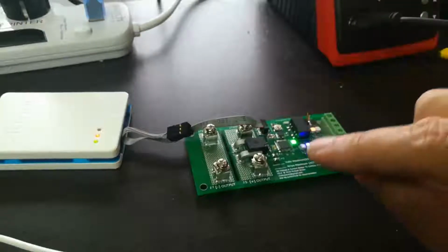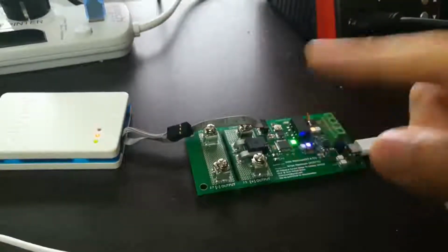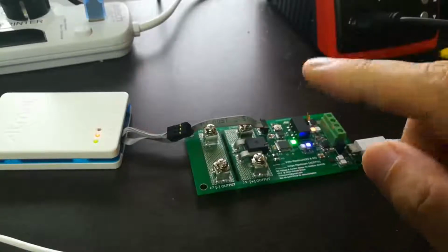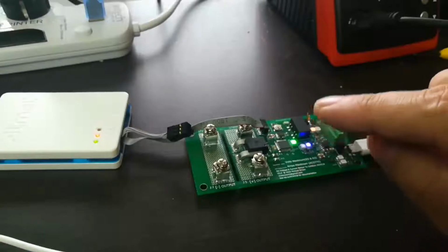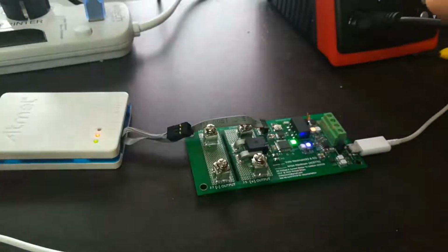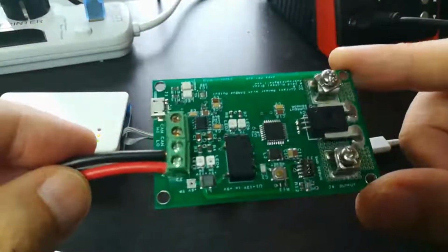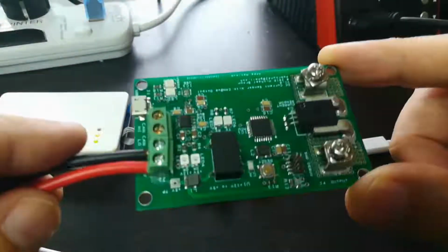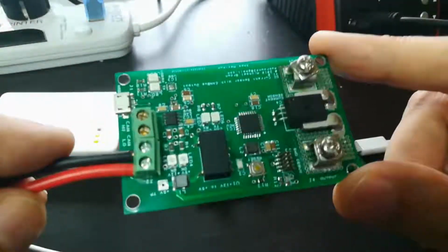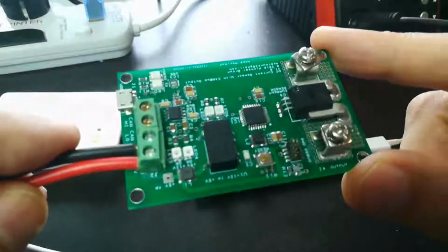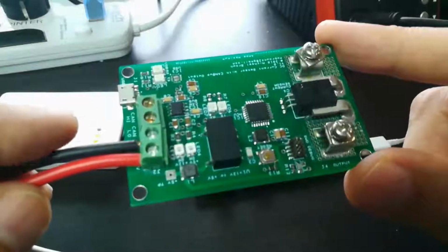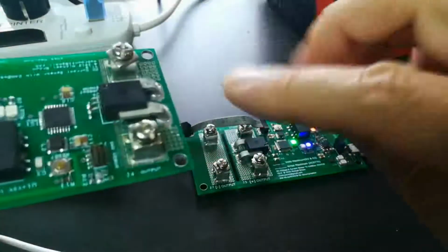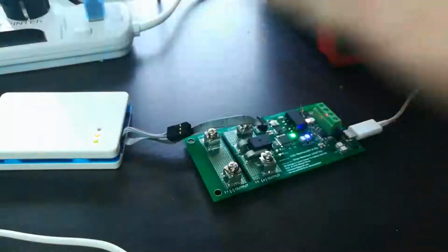I could have screwed something up with that and caused it to go into an infinite loop that it can't break out of. So I thought, all right, let me try the first version of the board that I did, which is here. It's still been on my shelf, and I had to hook up 12 volts to it. And guess what? I get exactly the same message, even without loading any firmware into this board. That tells me that the board isn't the problem. It's something from the board upstream.